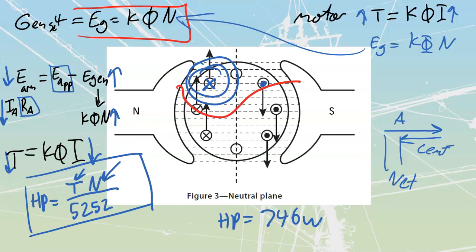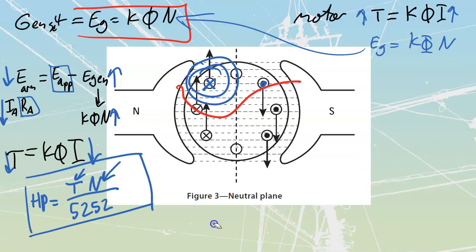Okay, speed regulation. Speed regulation is another formula that we deal with when we are looking at our motors. And speed regulation looks very similar to our voltage regulation. You guys remember looking at voltage regulation inside of the gensets? This is now going to be looking at our speed regulation, but it's almost the same formula. It is going to be no load minus full load over top of my full load. So we're basically going to say that, look, when a motor starts up, the motor is always going to start high, but then as we load it up, its speed is going to drop, right?